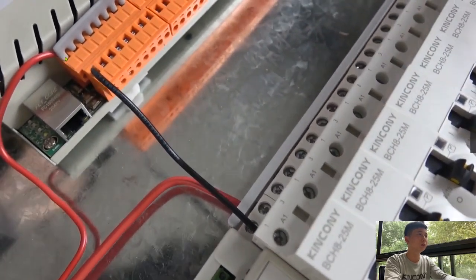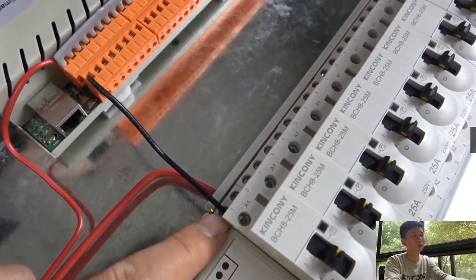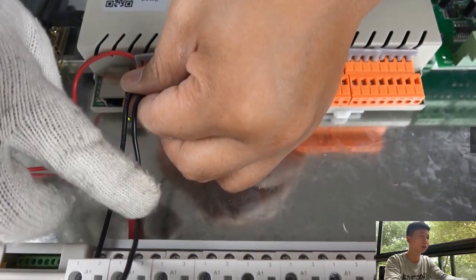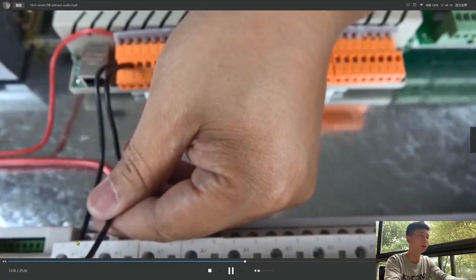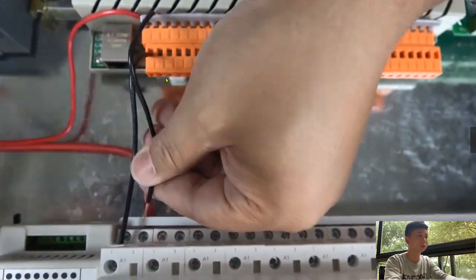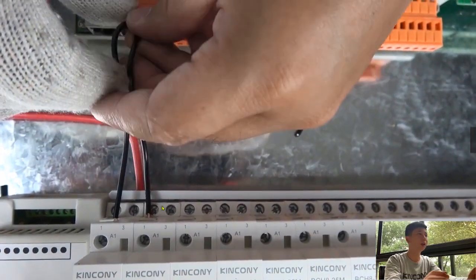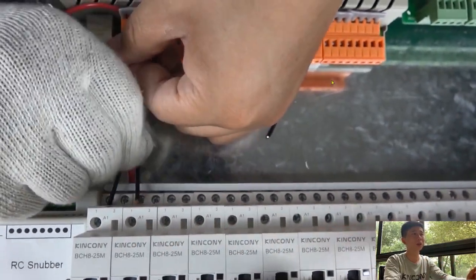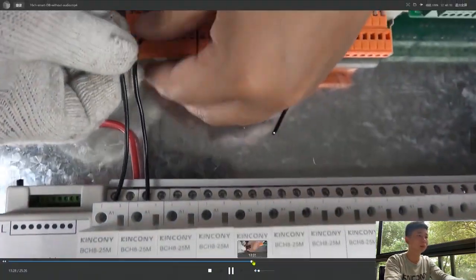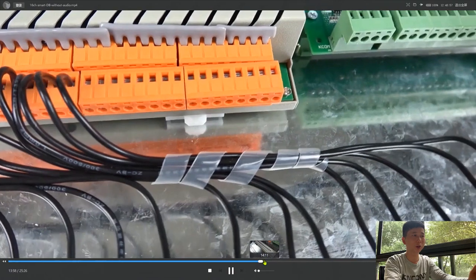And you can see this relay 1, L1 is in, and the output to the AC contact. This is L line in, and this black is L output to the AC contact A1. A1 is the coil, and this is the relay 2. Relay 2 also connects with the A1. So we need to continue until 16 channel, and let the green orange output to the A1. Now you can see we have connected with 16 channel output.